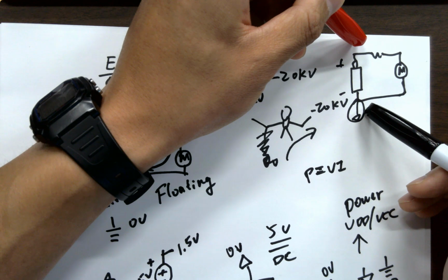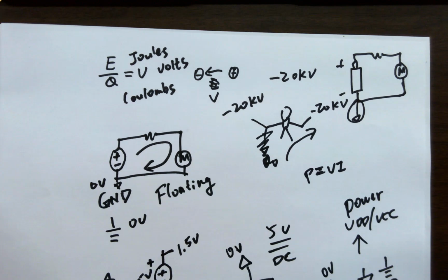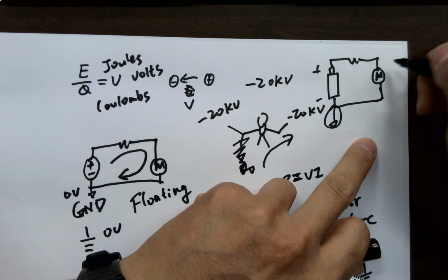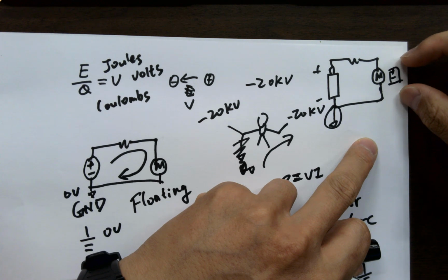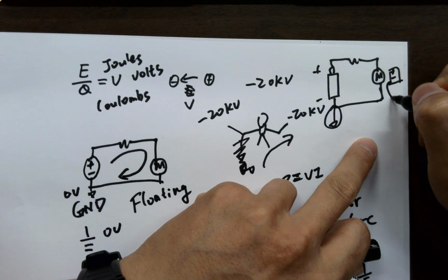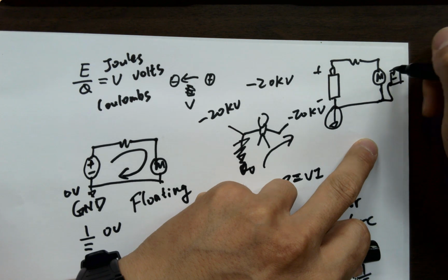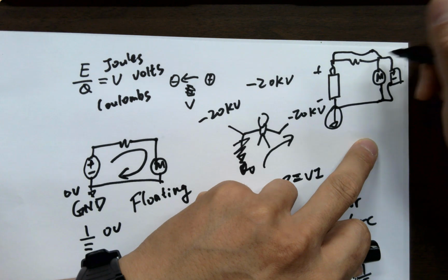It's not a physical part on the circuit. There are many other components besides a motor that need a reference voltage, for example a transistor or a chip. An integrated circuit has a plus and minus power supply on the chip. You always want to connect the minus pin of the integrated circuit to ground, and the positive pin to the power supply.